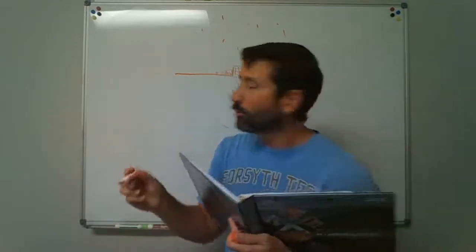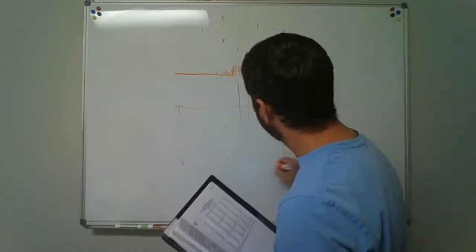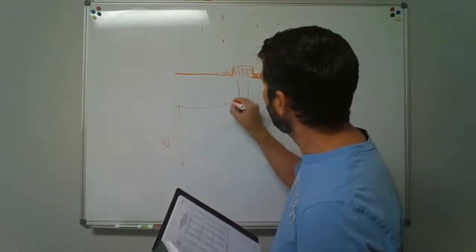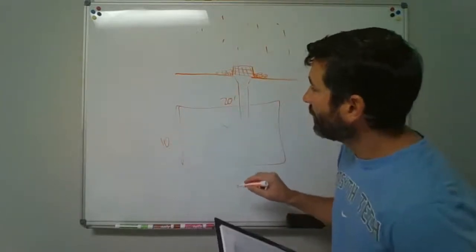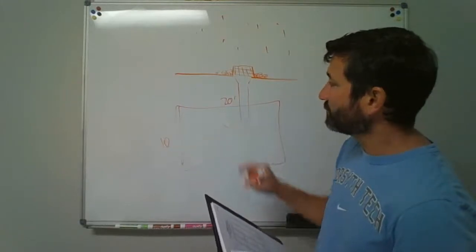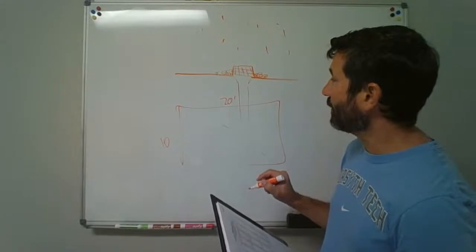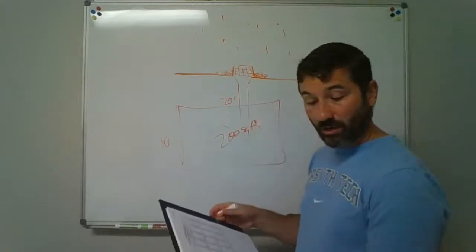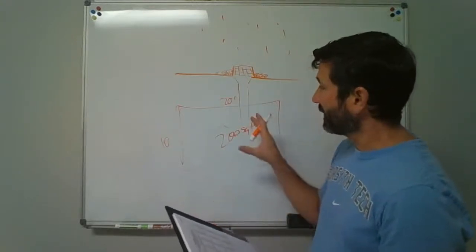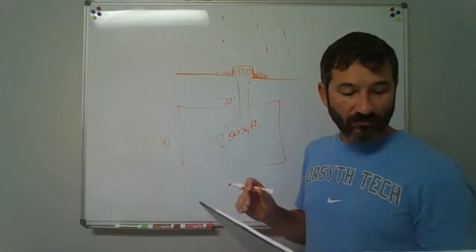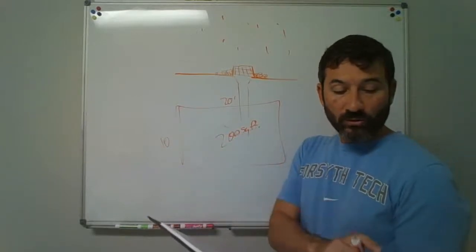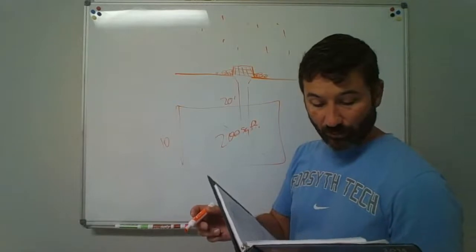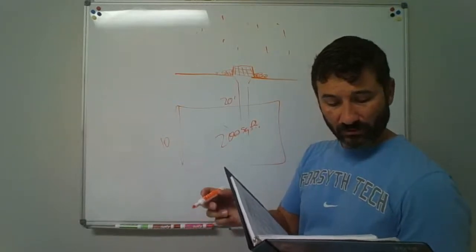So if you had a roof area, and we're looking at square feet, say this was 10 foot by 20 foot. How you figure it is you take 10 times 20, and you come up with 200 square feet. That's very small, probably, for a roof area, which is going to be greater than that. But what do you need? What diameter of leader are you going to need to carry however many square feet you came up with?